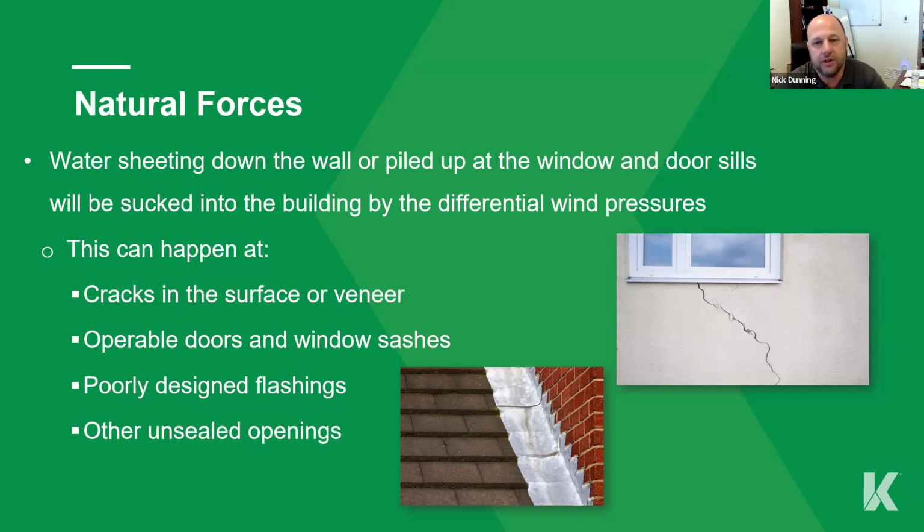And then flashing is one of the things I see done wrong a lot. And sometimes it's even backwards, where essentially they're redirecting the water that should be directed out into the building. They haven't been maintained, they're deteriorated. Similar to a weep hole that someone would seal up, that's actually going to exponentially increase that water intrusion because everything leaks. The only window that doesn't leak is a submarine window, and you definitely don't want those in your building. But we're redirecting the water. It's why we have weep holes. It's why we have sills and things that we'll install in some of these window systems. They're going to leak. It's not the end of the world. We just want that water directed out.